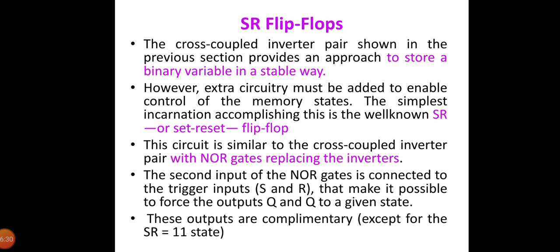The cross-coupled inverter pair, which was shown in the previous sections, provides an approach to store a binary value in a stable way. However, extra circuitry must be added to enable control of the memory states. The simplest incarnation accomplishing this is the well-known SR, or set-reset, flip-flop.